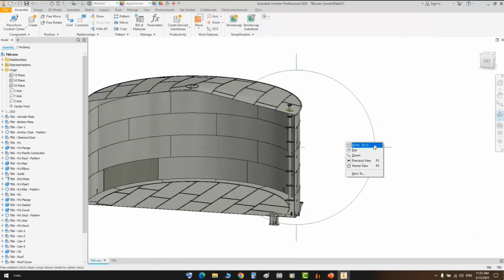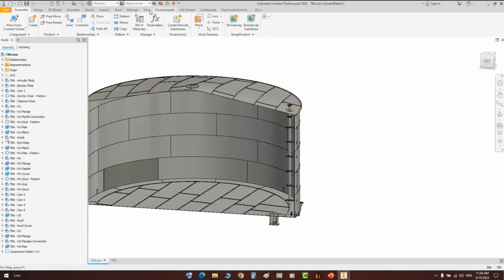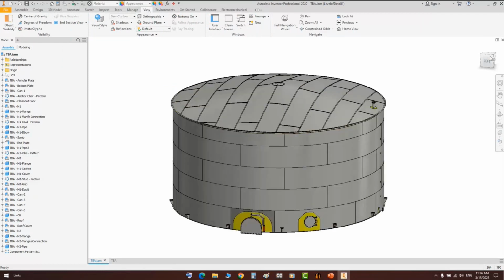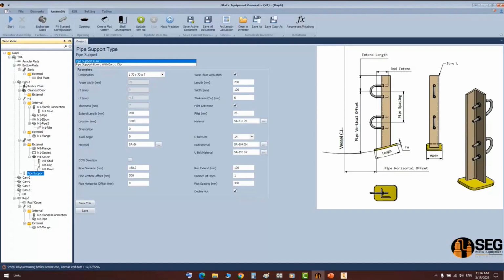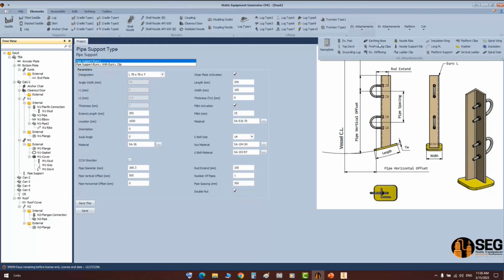Okay, now let's proceed with the next step, which is making the spiral stair. Let's remove the half section, and now let's add the first spiral stair, and we would like to make it with different levels, and how to describe the second or third or fourth or fifth level of the spiral stair. Here let's select the first can, and from elements let's select external, and from external let's select spiral.